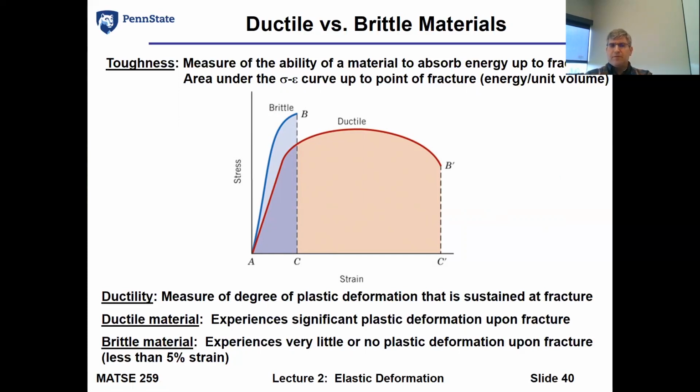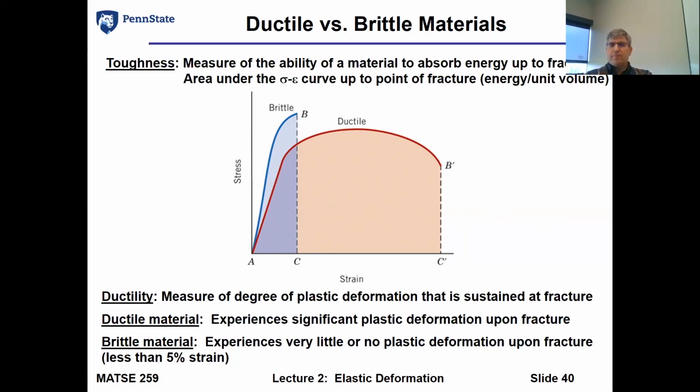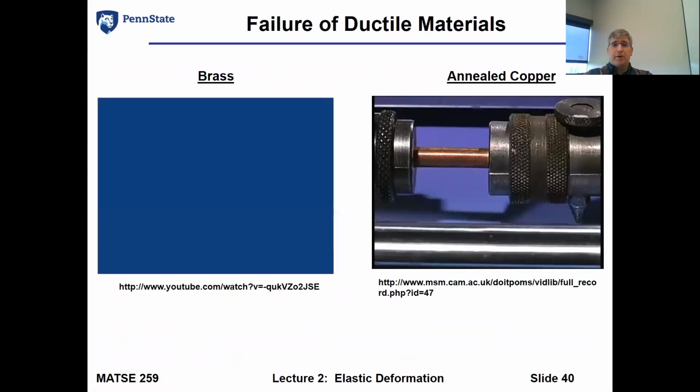The cracks may initiate, but if the material has high toughness, it doesn't allow the cracks to grow. So the cracks grow at a much slower rate. If you have a low toughness material, cracks will rapidly propagate and you will have failure much more quickly.